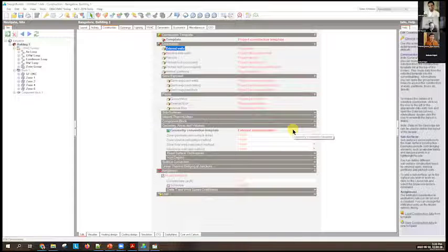You have a number of different options available in the help file. If you read it, you can find it. And always kind of remember, this is not a CAD file. This is a physics model. Sometimes the picture representation is not what you're interested in. You're interested in how is the building physics represented, or how is the HVAC system or the electric lighting system or whatever it is that you're modeling, how is that represented? Is that correctly represented or not? I don't know if that makes sense, but hopefully that does.